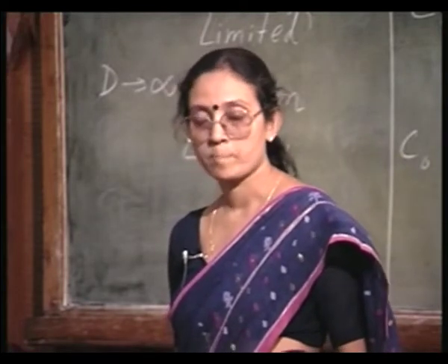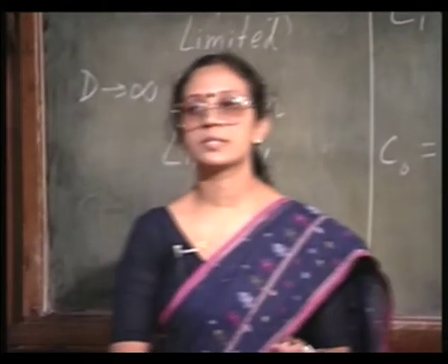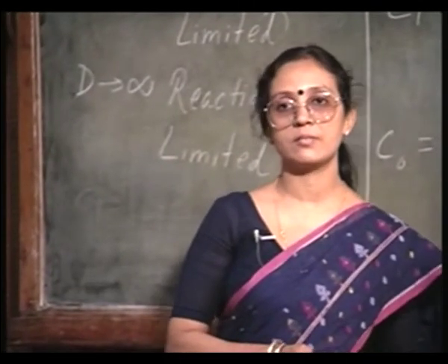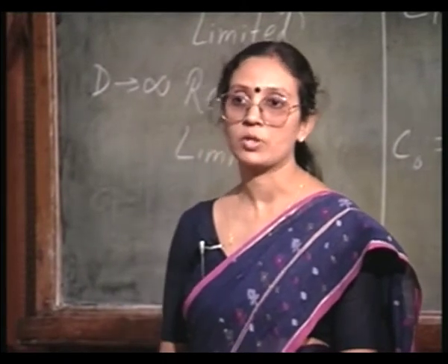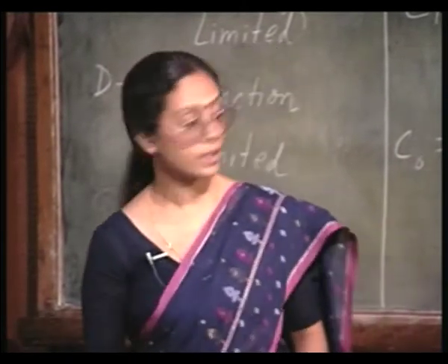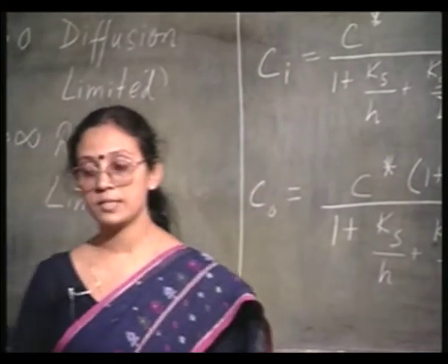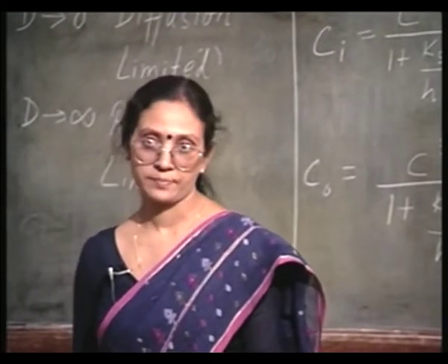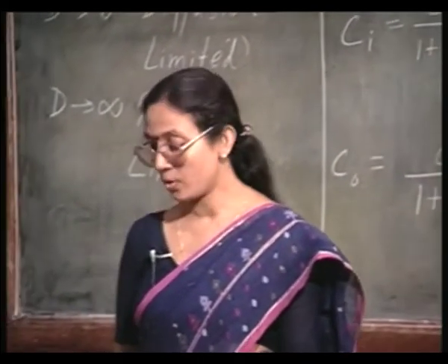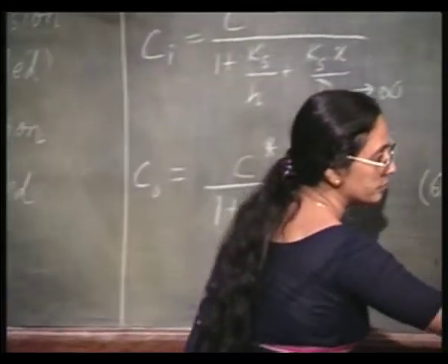Okay. So, now that we have obtained all these expressions for the fluxes, and from there we could relate the concentration of the oxidizing species with the equilibrium concentration and the known constants, we have to find out the oxide growth rate, right. How do we find the oxide growth rate? That is the next problem.